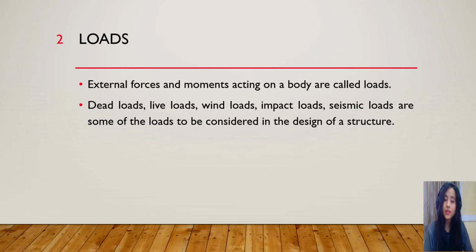So other loads such as dead load, live load, wind load, impact loads generally act on the structure very slowly and do not cause any rapid movements or vibration. So these kinds of loads are known as static loads. But this seismic load, since it causes vibration instantly in a matter of seconds, is not a static load. Hence the forces that come from seismic loads are different compared to other kinds of loads.